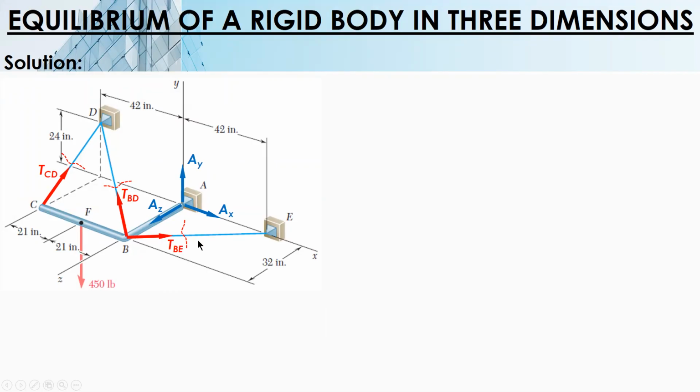Okay, so next is get the distances. Distance of CD, distance BD, distance BE. For CD, there is no X component. And so it's negative 32K, positive 24J. So we have this one, 24J. We follow the XYZ na what? Plus star, no? 24J and negative 32K. The distance is 40. For BD, you start from B, going to D, so move this way. That's negative 42, no? Negative 42. And then this one, negative 32, but K. K means negative 32K. And then you go up, positive 24J.